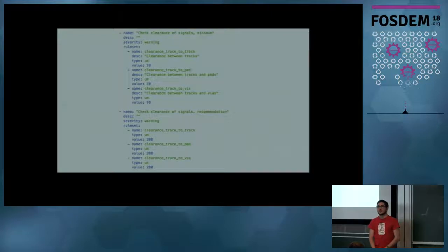So clearance is no issue at all? Of course it is. No. I mean, to define a clearance is not an issue because it just applies to the whole board. I have an example for the clearance. For instance, imagine you have some board that contains a high voltage power supply and some digital control electronics. You'd probably want small clearances in the digital part and pretty big ones on the high voltage part.